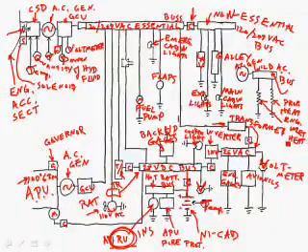It's hard to draw really, really small even with a tablet mouse. And of course you'll notice that this system right here, the wild alternating current, there's no way to switch on a bus tie contactor and get any of that power into the main system, or vice versa. Let's see. Oh wait, there's another place you can get power. You can get power from what we call external power. External power, that's this connector right here.